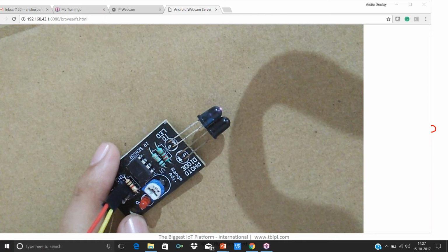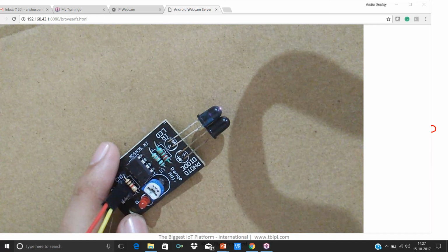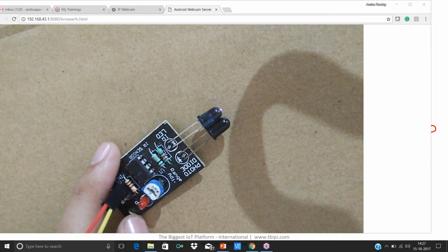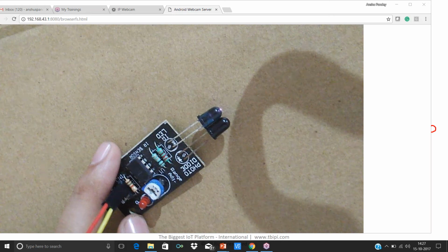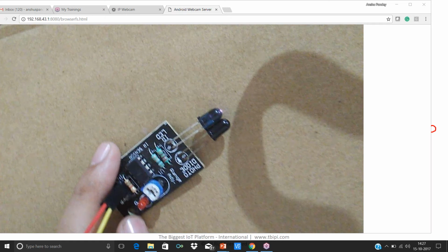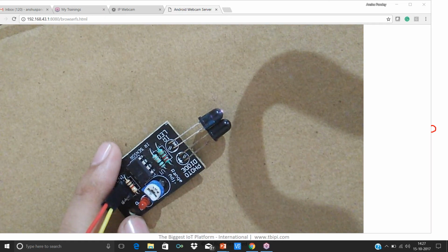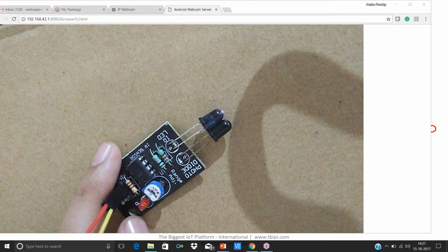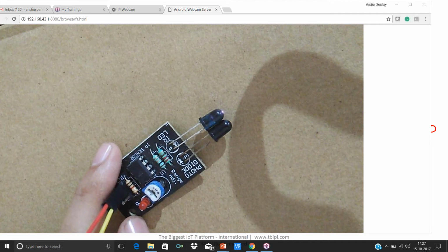there's a question, how many meters it will work. Well, the range of this particular sensor, proximity sensors, is going to be around 3 to 4 centimeters. Okay, so I mean, these proximity sensors are not meant for meters. For that, we have another sensor, that is the ultrasonic sensor, which is going to work around 2 to 3 meters. There's a question where we have to connect the wire in Arduino.